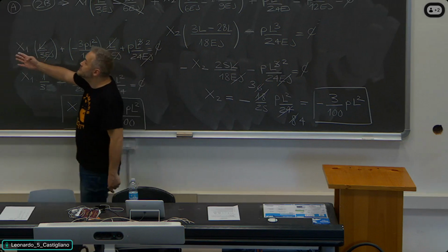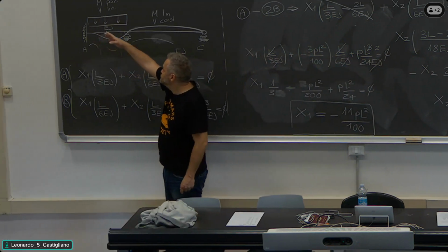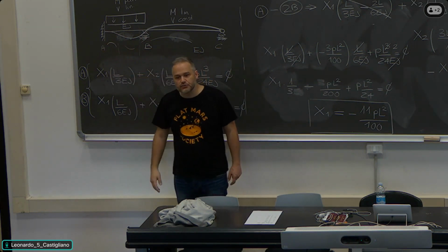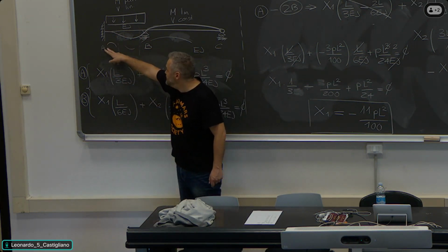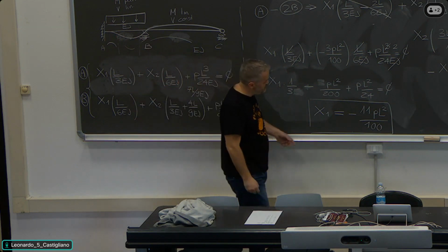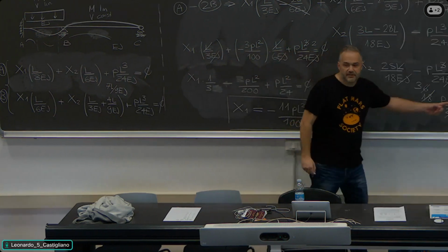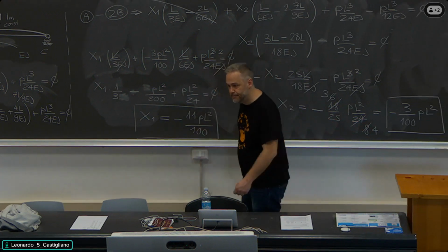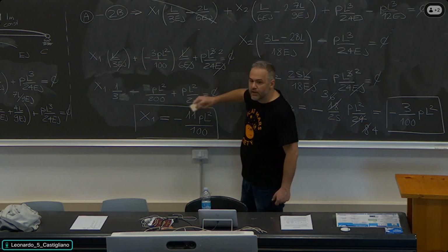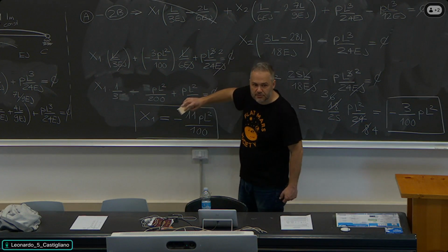What does makes sense mean? Since we said how the deformed shape will look, how it's supposed to be, I expect you to have a negative bending moment here and a negative bending moment over the center support, as I did. One is negative, the other is negative. Can I now cancel? I need some space to go on.